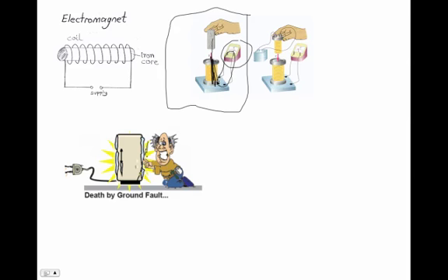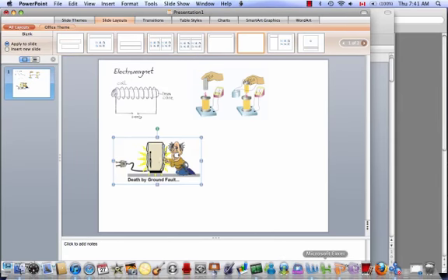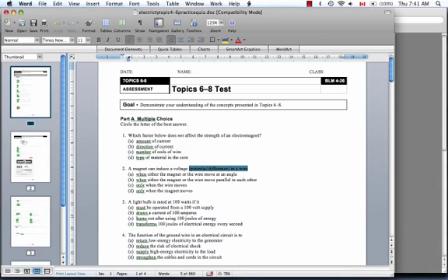So let's see which one applies to that. When either the magnet or the wire move at an angle. No, not an angle. When either the magnet or the wire move parallel. There it is. Yeah, so that's how we generate electricity using a generator. Only when the wire moves? No. Only when the magnet moves? No. So you could move the magnet, which is what I showed you, but you could also instead have a magnetic field, a horseshoe magnet, and you could spin a wire inside instead. So it works both ways.